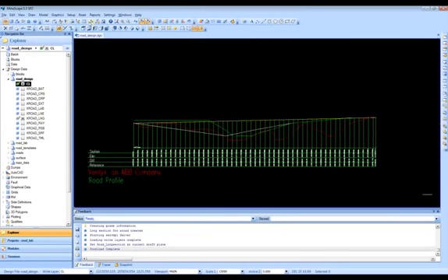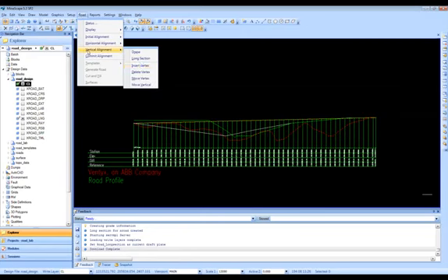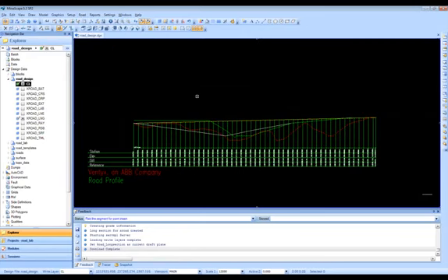So here I need to maybe enter in some vertical curves. So I'm going to go down here to road, vertical alignment, insert vertex, and I'm going to be inserting vertex on this flat graded line here, and I'm going to put some curves in here. You can snap to different things.